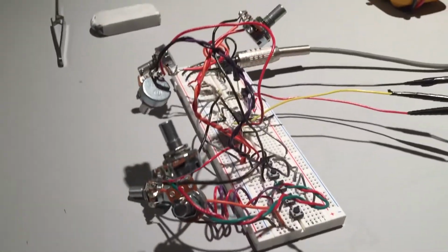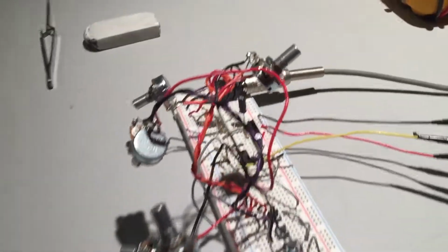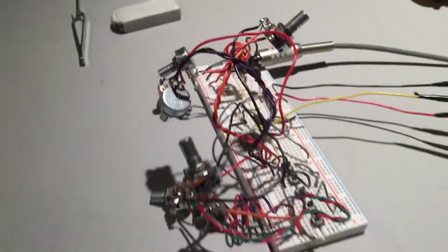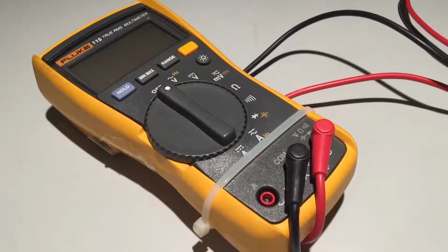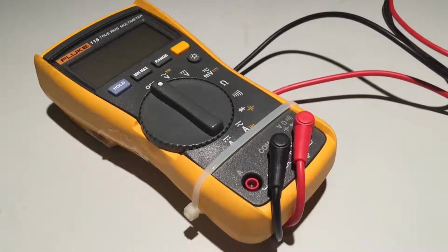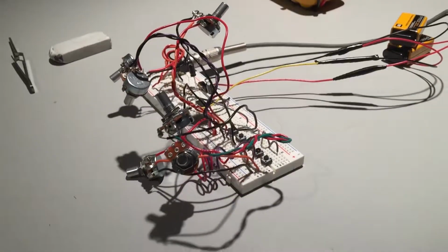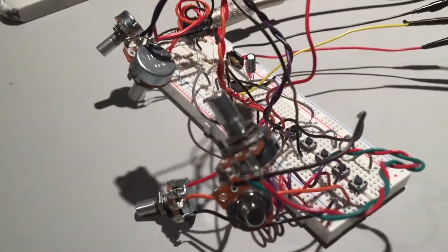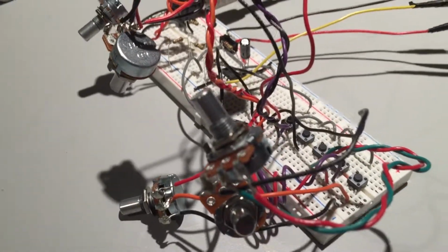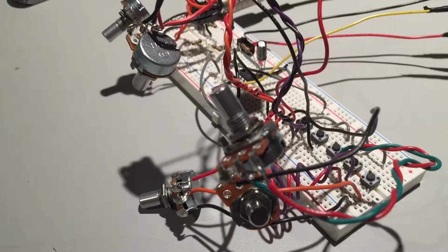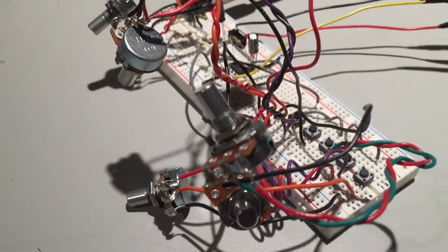We have 6 potentiometers. One of them is controlling the output volume here, so we're not really going to consider it. For each of the values that I had determined on paper, I then used a multimeter to fine-tune, so to speak, the resistance values of each of these potentiometers so that they were as close as possible to the values that I came up with theoretically.